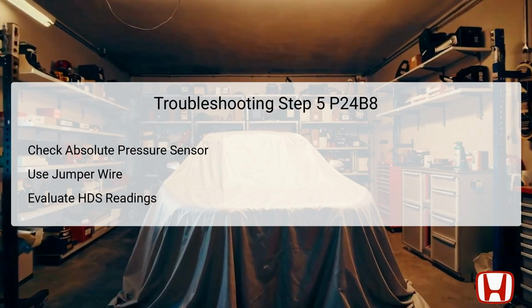If it does, that indicates the sensor is performing as expected, thus leading towards a resolution. However, if the sensor does not provide a reading beyond this threshold, be prepared for replacing the EVAP Leak Check Module to remedy the issue.